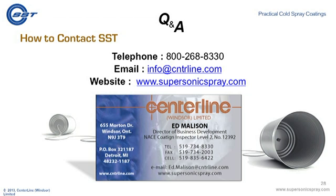We've got several existing customers right now using our cold spray equipment to remanufacture components that go into 16-cylinder diesel engine power backup supply. These are huge engines the size of a medium-sized car, and customers approach us for either coatings or application parameters to repair any of those components that go in there. Can we repair every single component inside those? No, but there's a good selection of components. I definitely look at that crankshaft. I'd need to know where the defect is, but I'm interested in working with the customer on that application.